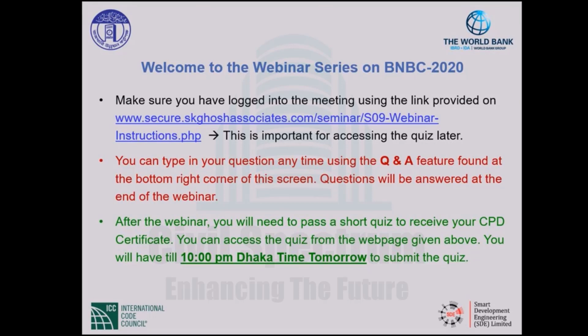I understand it can be done, but it's not easily done. So we take indirect ways of doing the second analysis. So that's the full answer to your question. It's a design device, so your analysis has to be according to what you have assumed, not what ETABS will do for you. Okay. Hopefully that is clear.